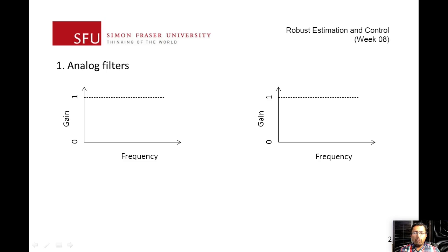Typically we don't want the filter to have too high of a gain. You don't want to connect your device to the filter and have it amplify the signal 10 times. That's not really the function of the filter. So typically we're going to assume that the maximum gain is around 1. There will be some variation, which we typically don't want, but nonetheless, we're always going to plot it from a gain of 0 to 1.